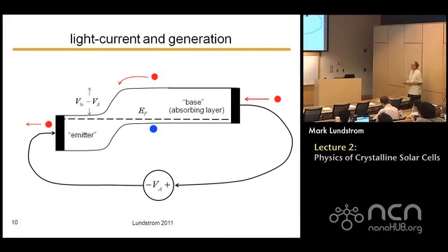So this is important. I remember reading a paper a long time ago by a very bright person. I read a lot of his papers. He wrote very good papers. But he wrote one where he said, but look at what would happen if the electron-hole pair were generated in the depletion region. Both the electron and the hole would be collected, and you'd get two amounts of charge flowing in the external circuit. But try it out as a little exercise.